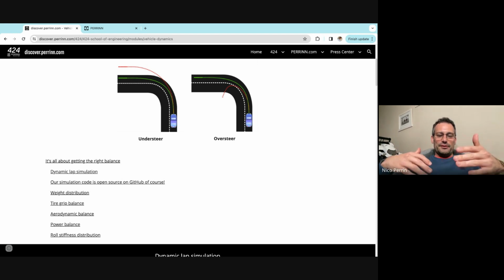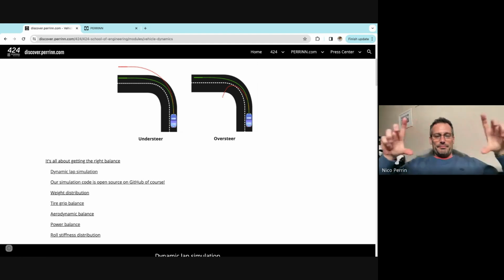But typically in mid-corner, when you're off brakes, off throttle, the understeer builds up quite quickly, and you get a big steering angle put in. So that disconnect between the oversteer and the understeer is a problem. And when you go back on throttle, typically with a very high steer angle, then it's the rear that snaps again, and you get back to oversteer. So you get oversteer, understeer, oversteer, and that big window of balance shift is described as the car being disconnected. So ideally, you want to reduce that window.